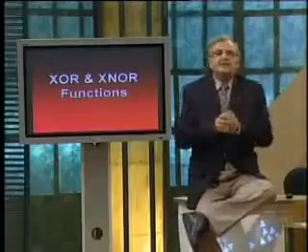Now, if you are going to be designing such circuits, then you don't need to design the odd parity generator circuit or the adder circuit or the comparator circuit. In fact, you can find integrated circuits which implement these functions. Such combinational circuits are known as combinational devices or functional devices. As I said, the most common functional device used is the adder. So let us start our discussion with adders.